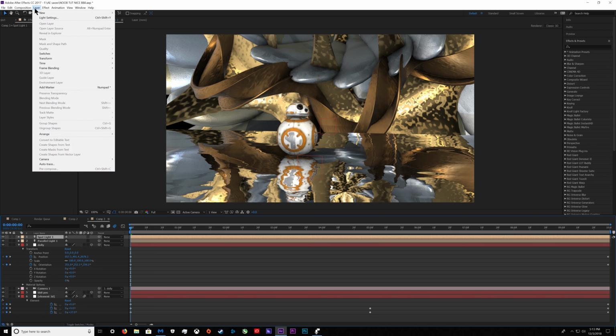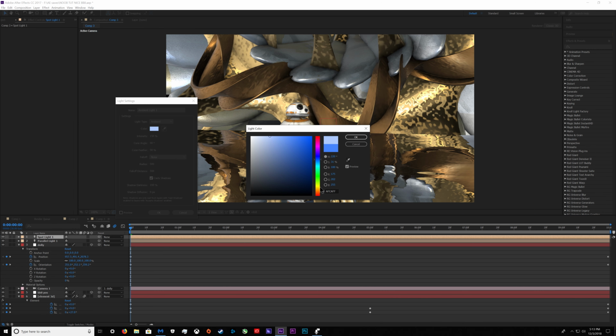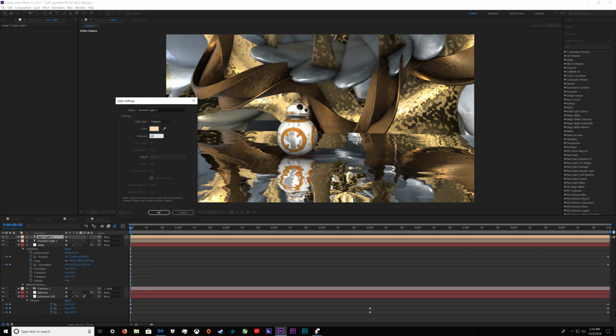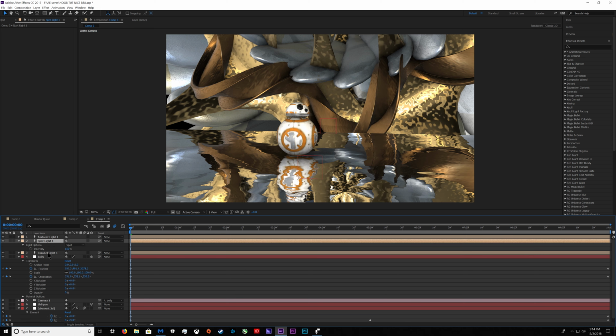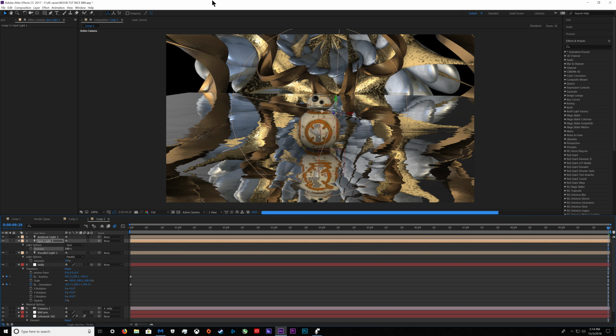And then we're going to add one more light. Make this one ambient, and it can really be any color you want. It's just an ambient light to add a little bit of fill. And then make this one like 20%. And then press T on these to bring up the intensity. Scoot back to the end so we can actually see the light. So here's our spotlight. For now we'll just turn down the intensity on the parallel to like 50, and we'll turn up the spot to like 250 so we can see what we're working with here.